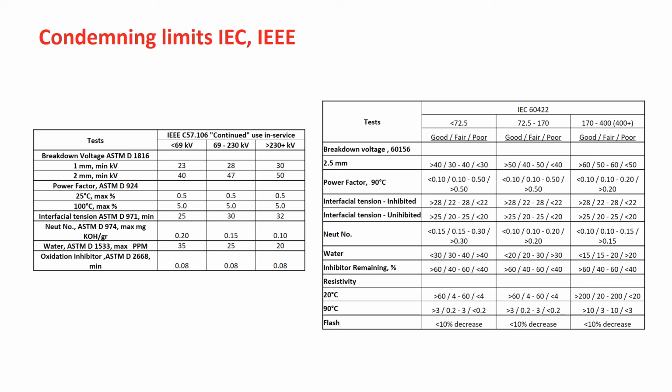You can see almost the same tests for IEC 60422. The only differences are tests for the oil resistivity at two different temperatures and the flash points of the oil. For more information and details, please read both the standards of IEEE and IEC.